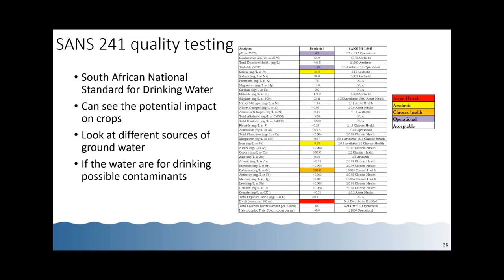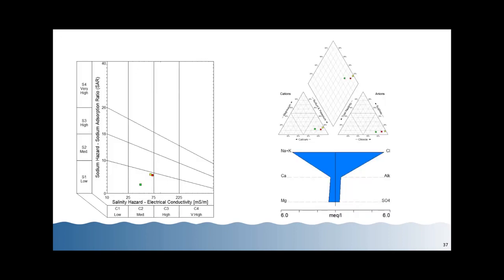drinking that water. Another concern with the metals in the water is quite often the groundwater is in a state where it doesn't have a lot of oxygen in the water, and so the metals are completely dissolved. And once we bring that water to surface, we oxygenate it, or even inside the borehole, just from the pumping process, we can oxygenate the water, and that can cause these metals to precipitate. And quite often that, coupled with microbiological contents that will feed on these precipitated metals, can cause clogging in the borehole and the pumps, and I'll talk a bit more about that in a second.